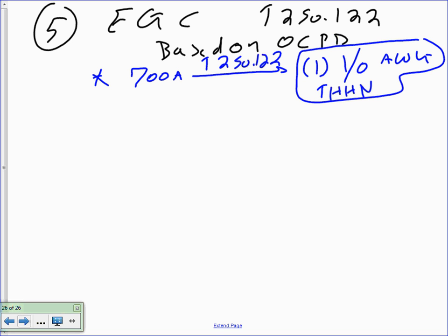Thank you. We need to, we're paralleling. I forgot that we're paralleling. So that will be 2 sets. You guys are on. Thank you. Yeah, 2 sets up, 1 aught. So you're going to put 1 conductor with every conduit.